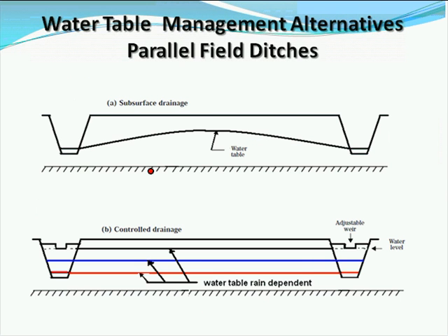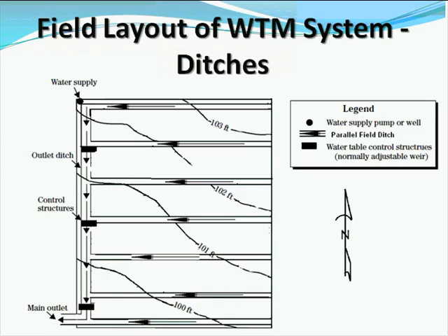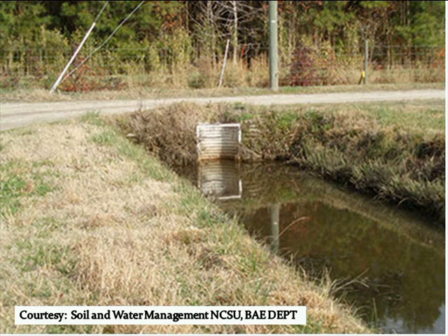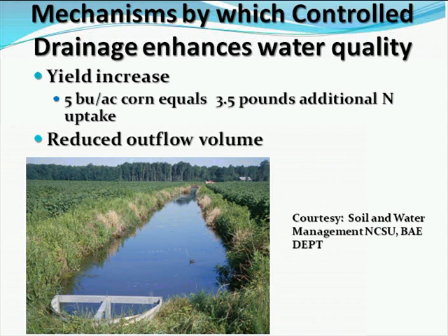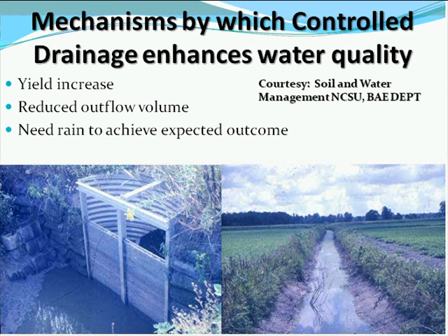But I did want to make this a very important point with a drainage system, especially as we get folks that are anxious to get out and work with producers on drainage water management. We need to know that you've got some type of restrictive layer down that's holding the water up, so that you have a manageable water table and something you can count on, and not just somewhere down below it's bound to be backing up or we wouldn't be seeing a water table.